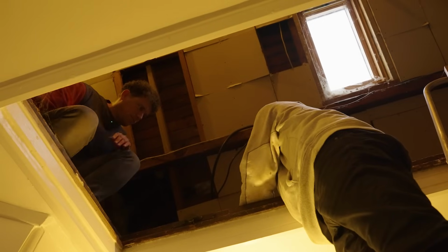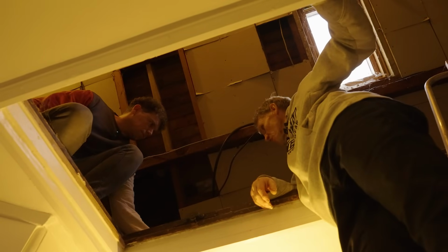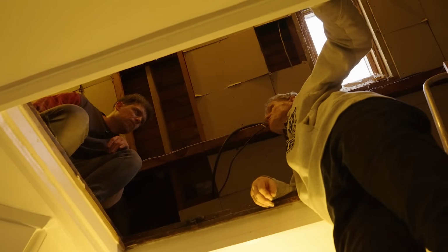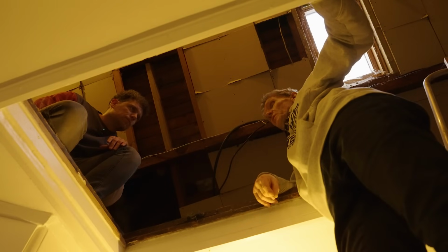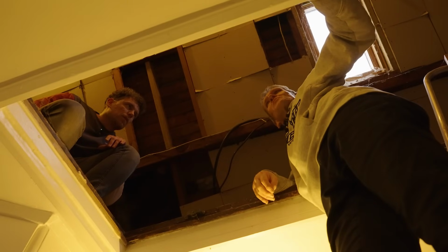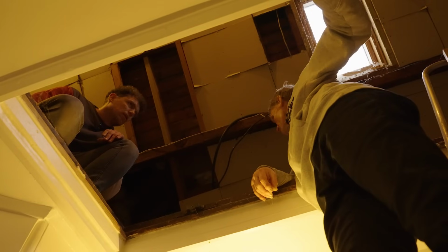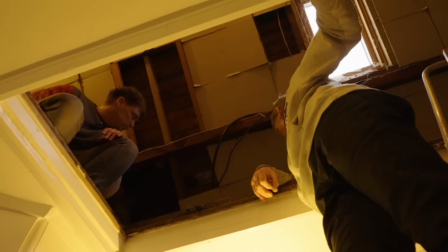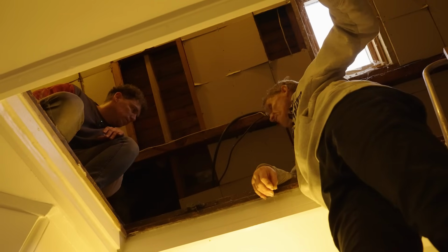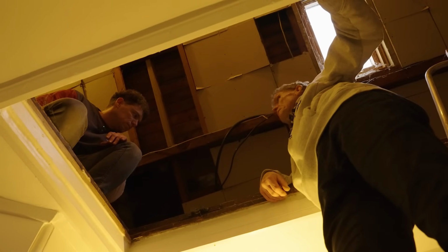Yeah, it's a bit of blown fibre in there, and the trouble with that blown fibre is it does blow around as well over the years, so it's not evenly distributed. But it's only at best 2 inches thick. So we're now looking for 9 inches, 12 inches, 300 millimetres of loft insulation. So you can see that you need another 10 inches in there. But even if you didn't come up to modern standards, putting another 6 inches all over would definitely be worthwhile. Definitely transform this space.